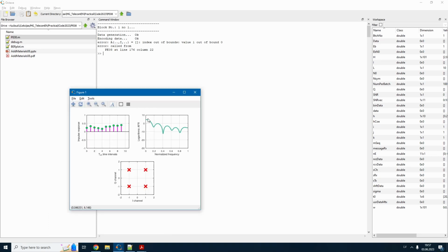So here you can see the amplitude frequency response of your channel impulse response, and analyzing this we can see that it's not really bad. It's just that it attenuates the signal. So if our desired spectrum would have been in this part, some part of the spectrum would be amplified, some part would accordingly even have some fading at this frequency, for example. As for noise, the noise is accordingly suppressed more or less by this channel.